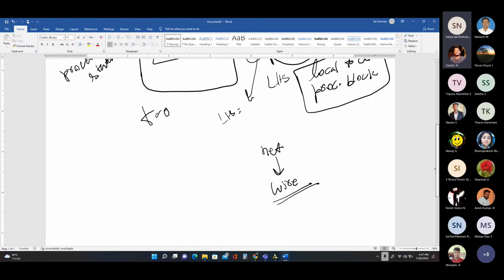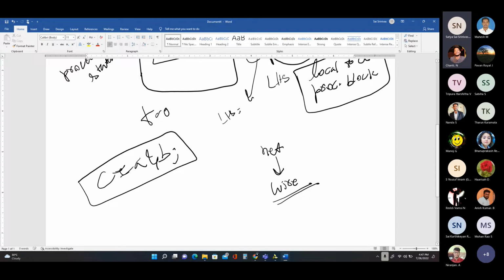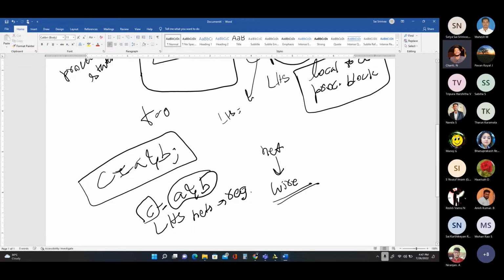And one more thing, if C is equals to A ampersand B is a procedural statement, you have to write this inside a procedural block. Inside a procedural block, all the left hand side nets should be of reg data type. The right side nets, that is in this example A and B, can be anything. It can be a wire or it can be a reg, but the assignment to the left hand side should always be a reg data type.